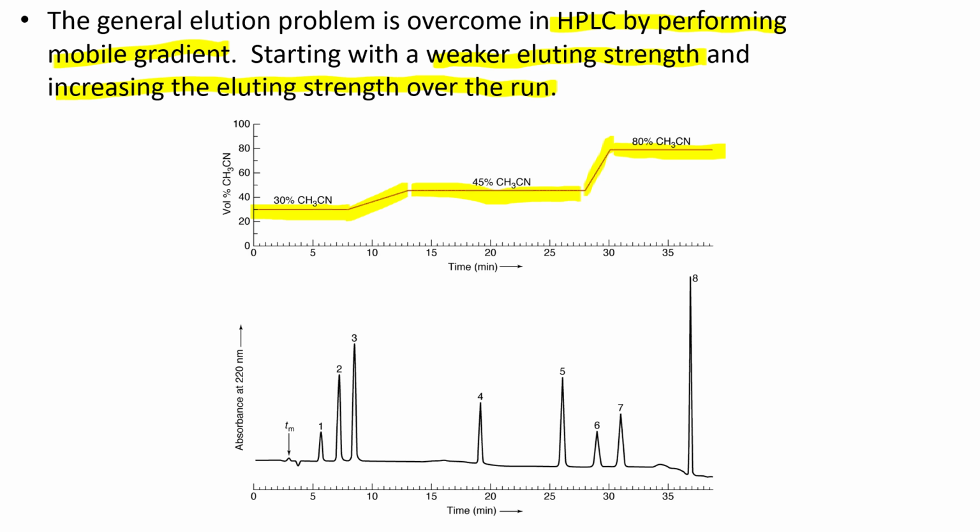And I would tell you that if I'm the designer of this, and they've designed this run where it's happening within 40 minutes, they're getting all things off the column. Sure, I would say, yeah, that would be great, but there's just too much dead time in here. It's great resolution, but you're wasting too much time. All this time you're pumping the mobile phase at 1 mil a minute. If it's hydroorganic, that's money.